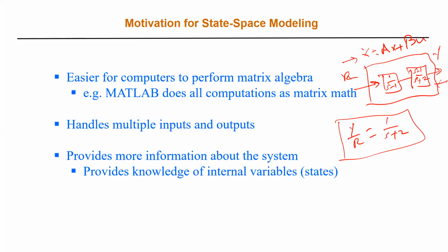But if you write the differential equation or the state space representation for the system, which is second order, with x1 and x2, you will see that the eigenvalues of this matrix are such that one of them is positive and one is negative, which means the system is going to be unstable.